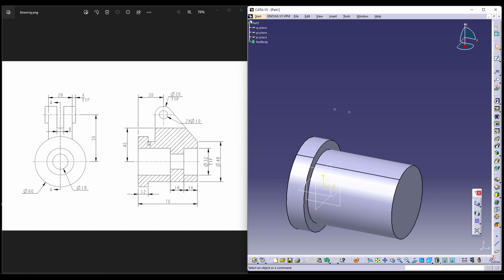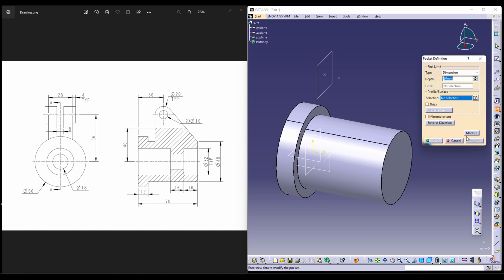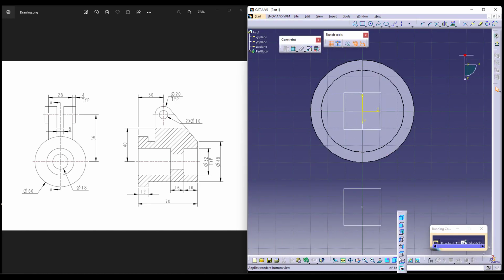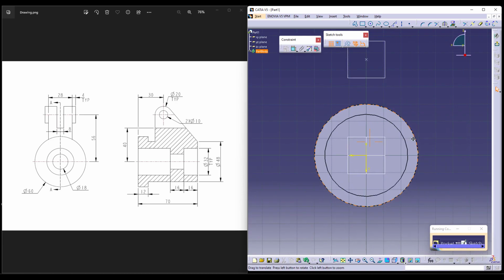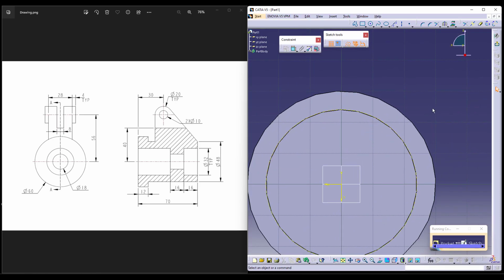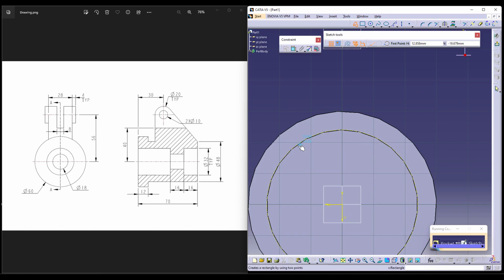To make the shape, whatever slot cut I am supposed to make is till this plane, this point. So I'll take a plane at that location, making it parallel, and then start making my sketches to remove the shape. Again, I'll be using the right view to make the cut. I'll require this as a reference. Let me start making the line as well as make the cut.